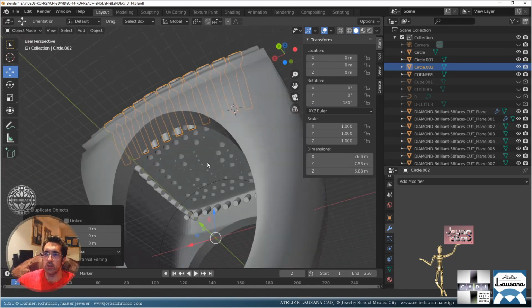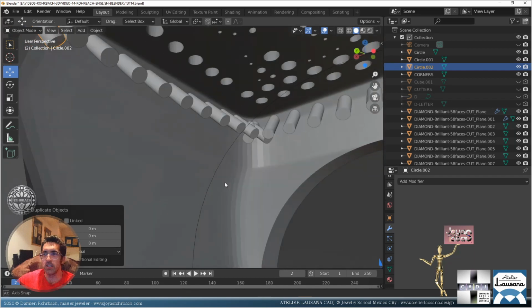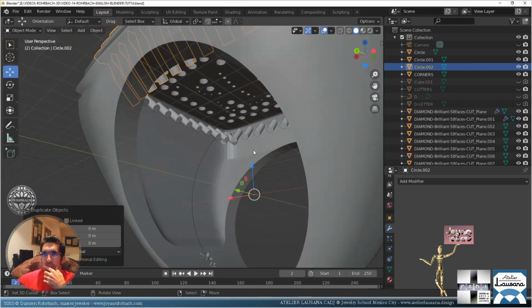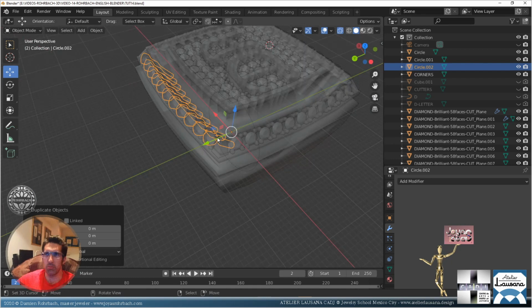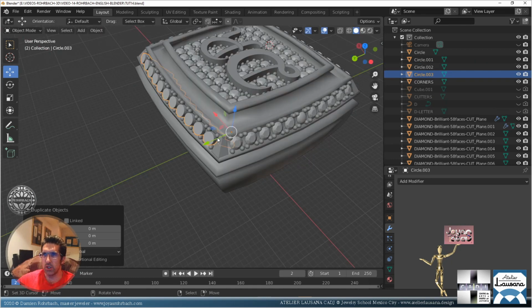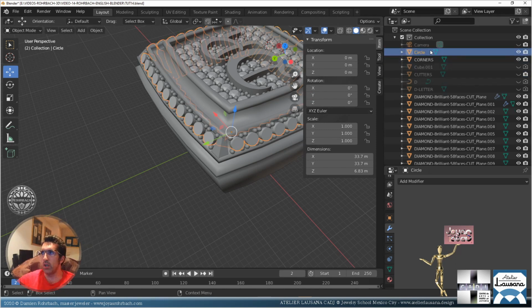Okay, now there at the corner, I just want to see. Yeah, these two holes are going to be overlapping at the corner somehow, but it's going to look good. It happens from time to time. Shift D, 270. Now these guys, Control J, secondary cutters, I should call them.